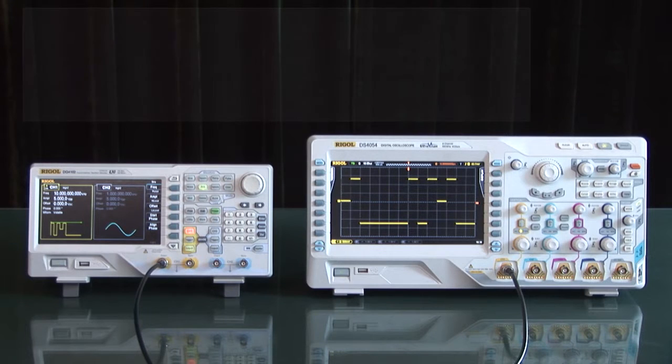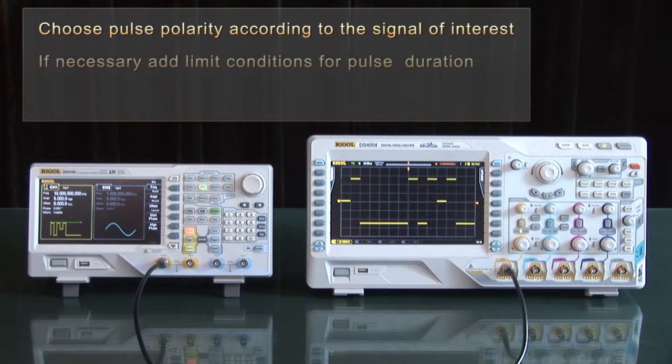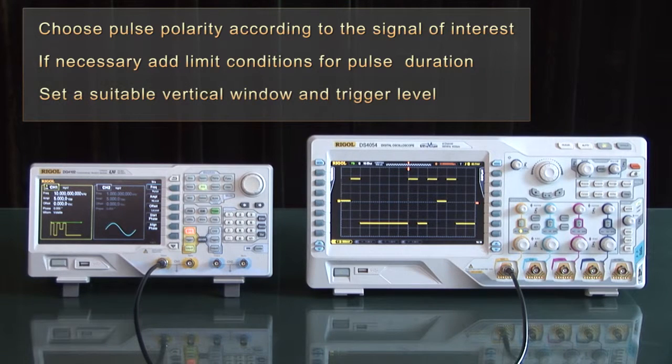Here are some key points. You want to choose pulse polarity according to the signal of interest. If necessary, add limit conditions for your pulse duration, and then set a suitable vertical window and trigger level.